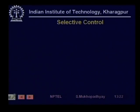So, this is cascade control, very common and gives significant performance improvements over very affordable costs in most cases, and therefore, is widely used. Now, we look at some other control structures, namely selective override and split range control. So, first start with selective control.